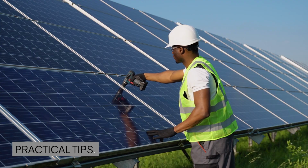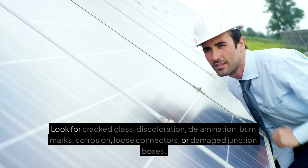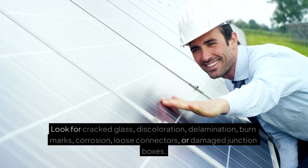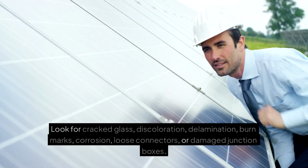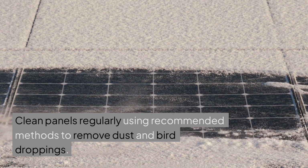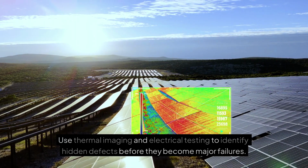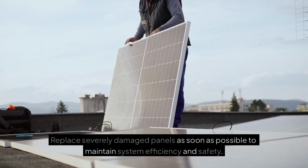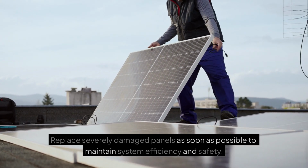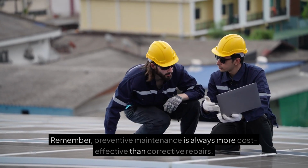Practical tips. Always inspect PV panels during routine maintenance. Look for cracked glass, discoloration, delamination, burn marks, corrosion, loose connectors, or damaged junction boxes. Clean panels regularly using recommended methods to remove dust and bird droppings. Use thermal imaging and electrical testing to identify hidden defects before they become major failures. Replace severely damaged panels as soon as possible to maintain system efficiency and safety. Remember, preventive maintenance is always more cost-effective than corrective repairs.